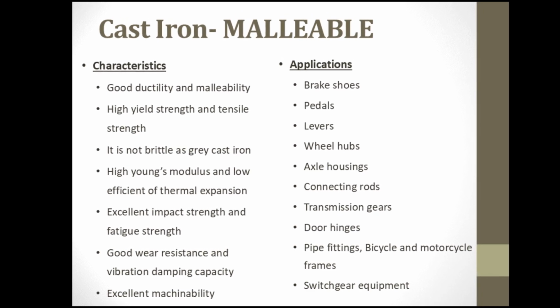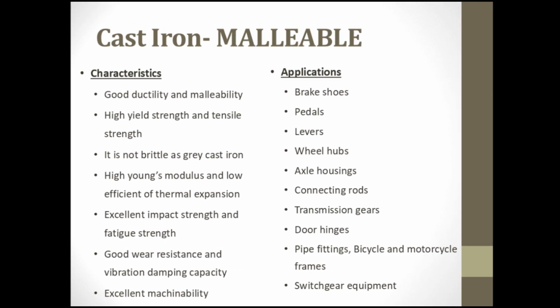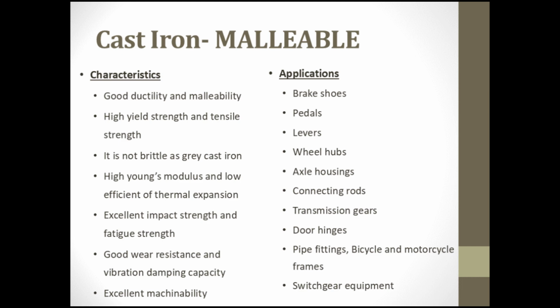Cast iron malleable characteristics: good ductility and malleability, high yield strength and tensile strength. It is not brittle like grey cast iron. High Young's modulus and low coefficient of thermal expansion. Excellent impact strength and fatigue strength. Good wear resistance and vibration damping capacity. Excellent machinability.